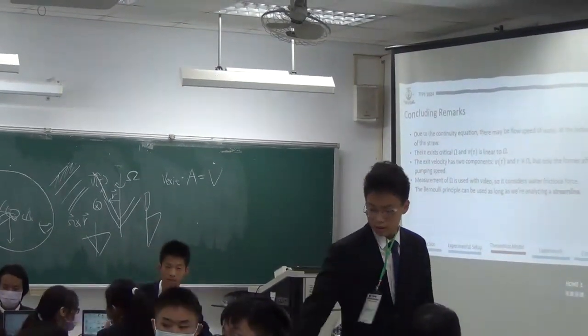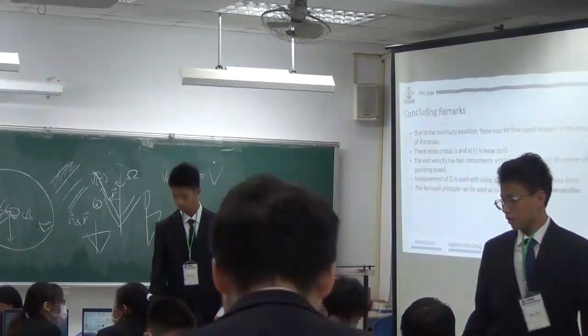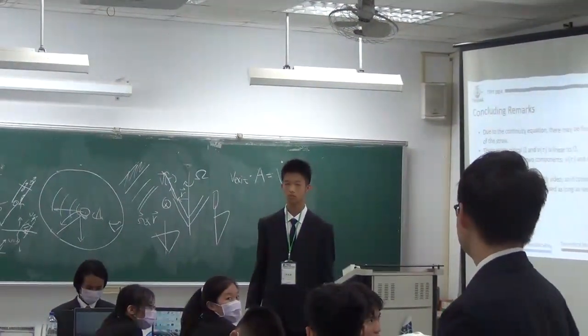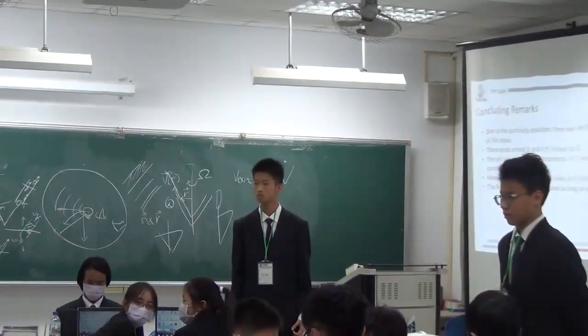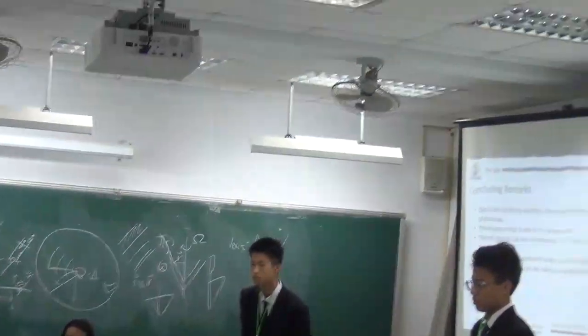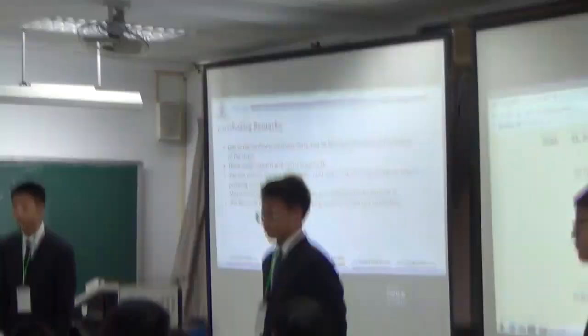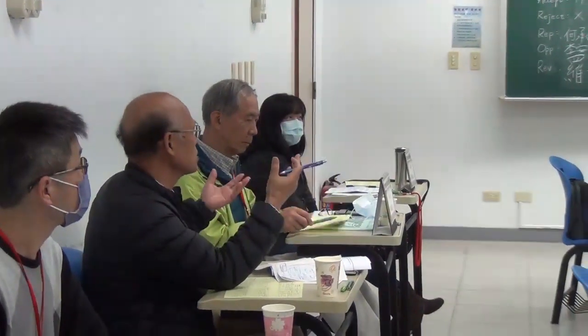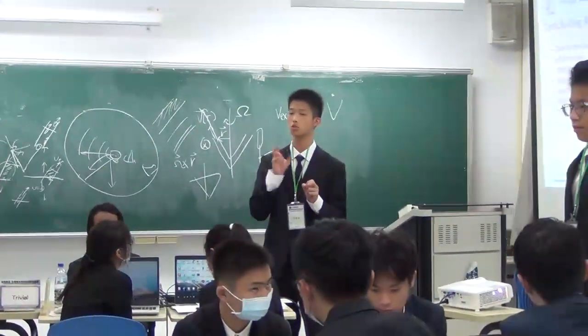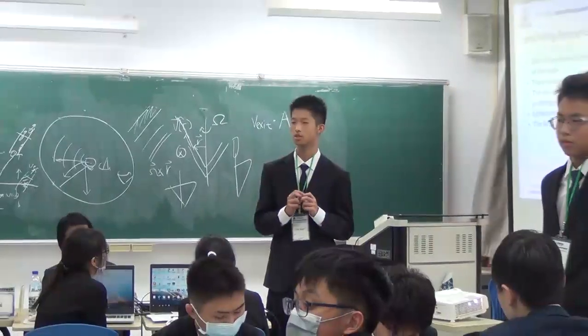Now, a question for the reporter. At some point you mentioned that the Reynolds number was too high, so the flow was kind of turbulent, right? Would that be a problem for using Bernoulli's equation to make this fit? I think as long as we are analyzing two points in the straw in the water, we can use Bernoulli's law.